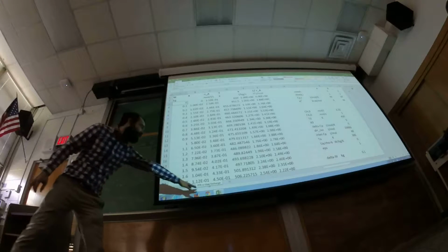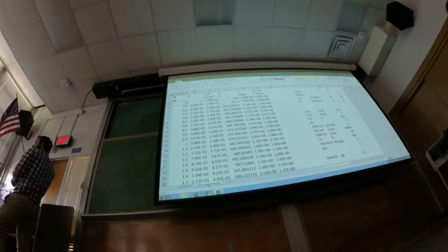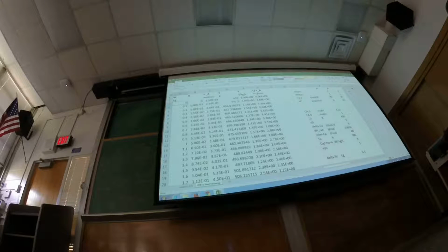Okay, so here's the PFR with heat exchange. So what are the differences? Now I'm doing this in terms of weight. Here's conversion. I did put in the rate. I find it easier at some point to just have the rate as its own column. Temperature, rate constant, and then 1 over the rate so that again we can look at Levenspiel. Here's the inlet, so the stoichiometries. The thetas, that should be 0.